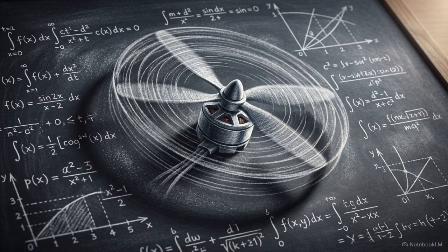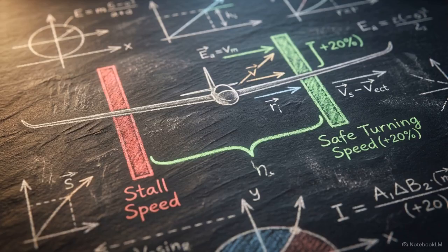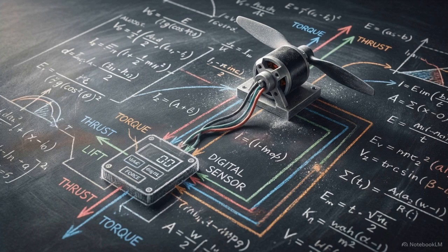To ensure the airframe remains controllable under these stresses, we must deliberately step away from the absolute aerodynamic optimum, injecting a strict 20% margin above the turning stall speed. With our required aerodynamic power established, those theoretical forces must be translated into physical mass.